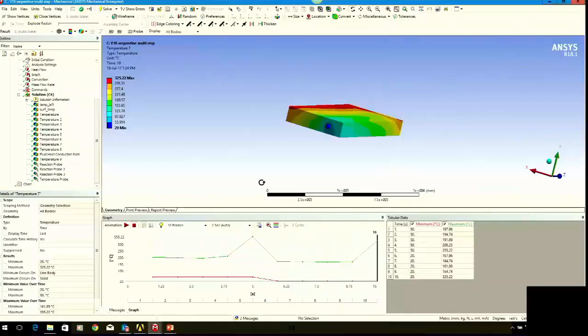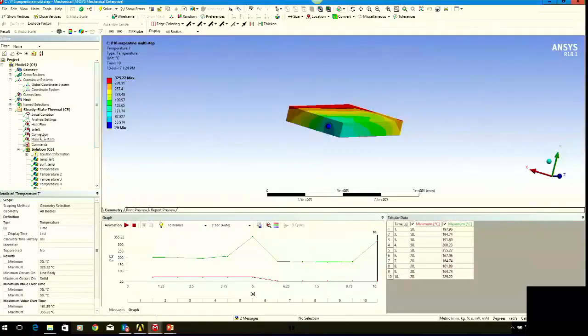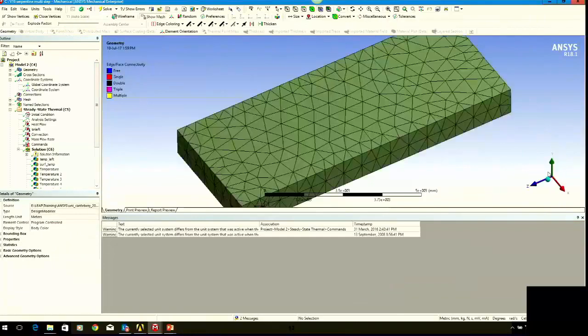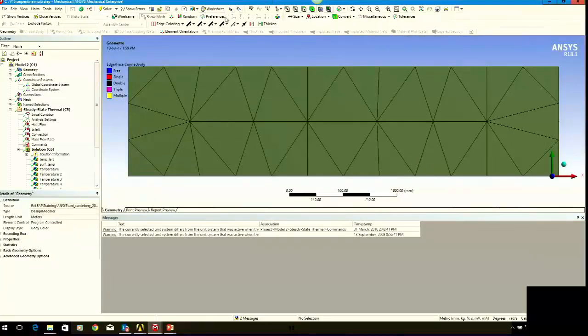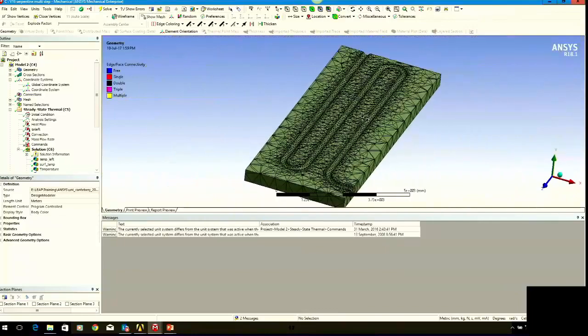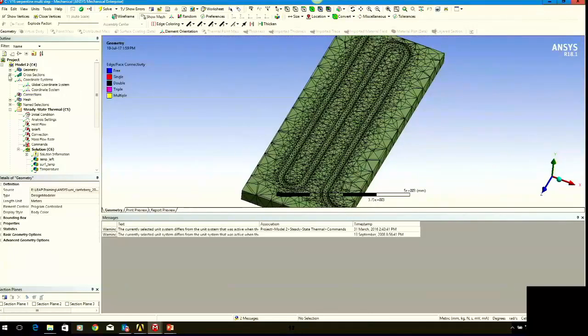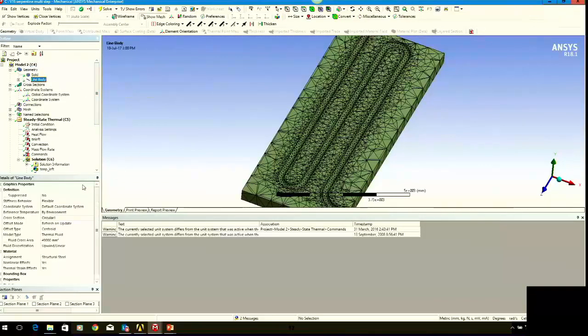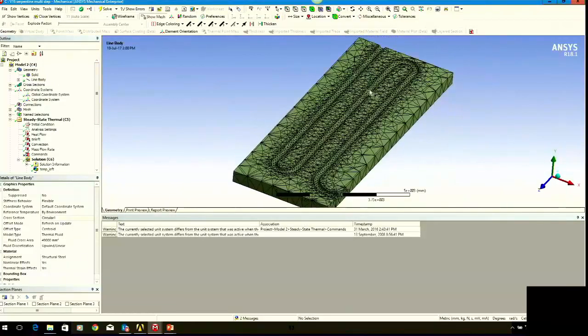So in this model here, this is basically a steel block. So let me just do a cut through this block. Okay, so on the inside of this block, there's basically a cooling channel that loops through, and then there's another line element which is basically assigned properties of a cooling fluid, and then we assign a temperature at the inlet and then a mass flow, and from that it's able to calculate the heat that's picked up by the fluid that's flowing through here based off its properties, and also the heat transfer coefficient on the wall.